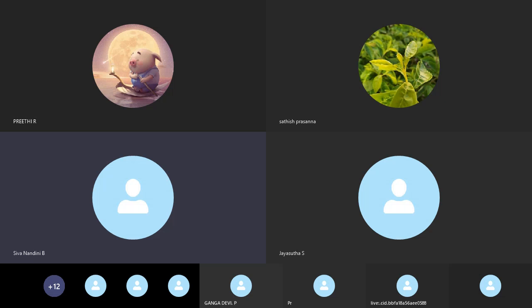Go to slide number 19. Slide number 19 shows an example of netlist information. The netlist has a header. That header includes the name of the netlist. Next, we have the date and time at which the netlist was generated. Next, we have the processing time, 6.4, given in milliseconds. That is the time consumed for converting the schematic diagram into a netlist: 6.4 milliseconds.